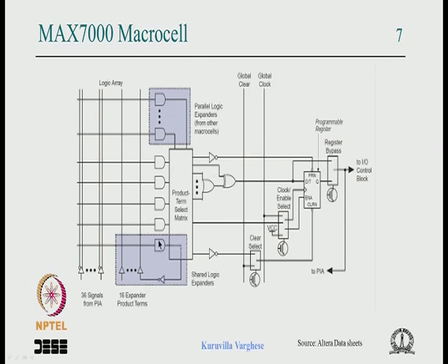Once again the problem remains here: these AND gates are very wide. There are a lot of inputs, 36 variables and their complements can be connected to the AND gate, which is very rarely needed in real life cases. Such a structure makes the 36 signals, and the programmable interconnect array or crossbar, very big, which doesn't make it scalable.